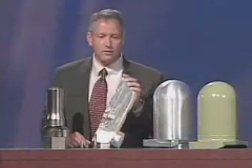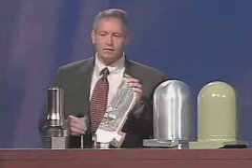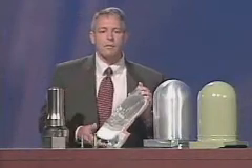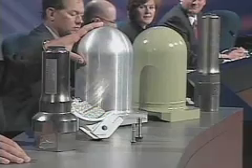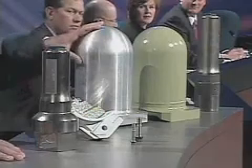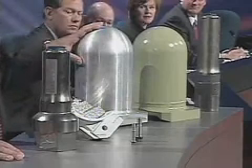And what that allows us to do from a physics standpoint is it extends the length of time by which we decelerate this bolt half. It extends the distance by a short amount. It decelerates over a longer period of time, and so what that does, it decreases the forces that the bolt catcher structure has to withstand. So we sort of attacked both sides of the equation relative to the bolt catcher. We've significantly increased the capability, but we've also decreased the forces that the bolt catcher has to withstand.